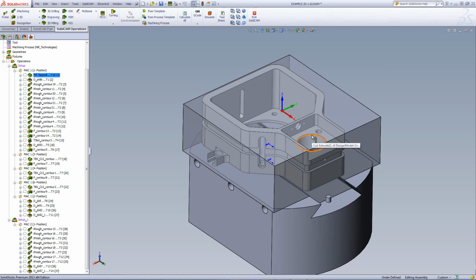Now, for this hole I have over here, and for this area that I have over here, I'd like to do a pre-drill operation that would allow me later on, when I do the iMachining operation, to go directly into those holes to mill out those areas with iMachining.